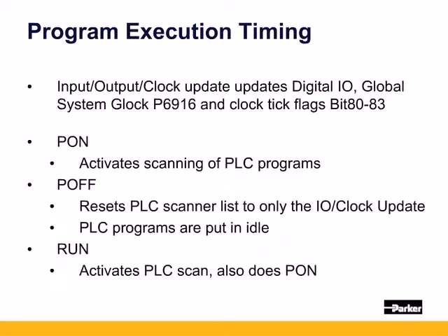The ACR9000, 8020, and 1505 have a maximum of 200 command lines of the machine code. Note that this isn't rungs. I'll show you this next. All other ACRs are limited to 100 command lines. Also, the AcroPLCs can only use a maximum bit number of 8191.